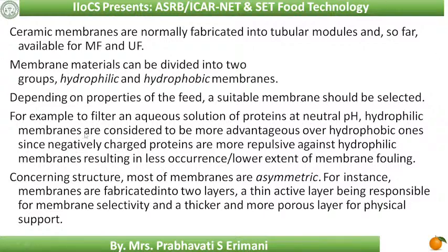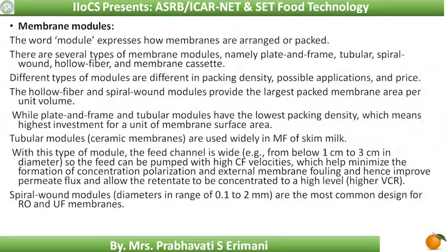For example, to filter an aqueous solution of proteins at a neutral pH, hydrophilic membranes are considered more advantageous over hydrophobic ones, since negatively charged proteins are repelled by the hydrophilic membranes, resulting in a lower occurrence and lower extent of membrane fouling. So this is hydrophilic and hydrophobic, and the membrane will be selected selectively.